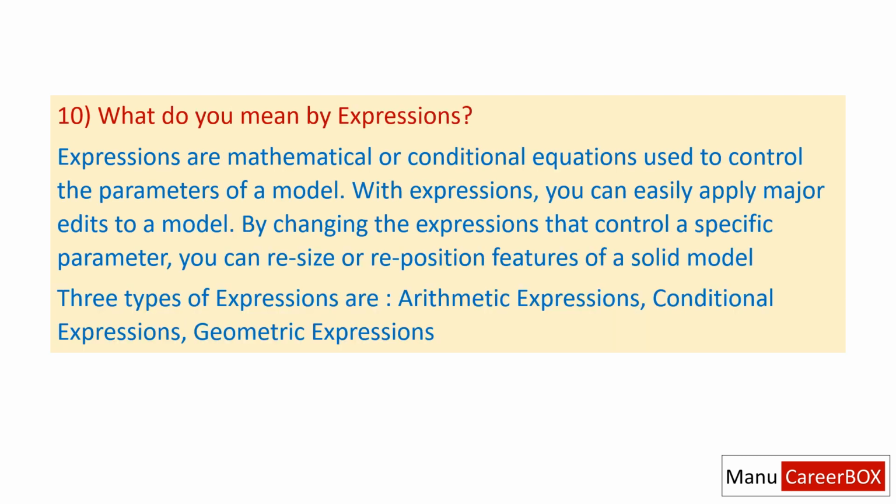10. What do you mean by expressions? Expressions are mathematical or conditional equations used to control the parameters of a model. With expressions, you can easily apply major edits to a model. By changing the expressions that control a specific parameter, you can resize or reposition features of a solid model. Three types of expressions are arithmetic expressions, conditional expressions, geometric expressions.